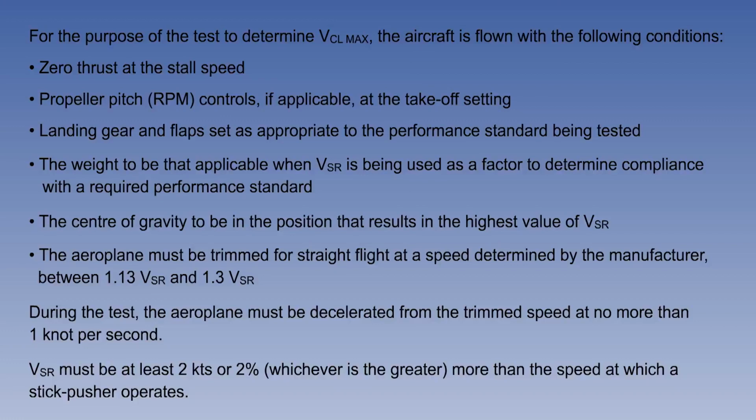VSR will vary with each of the conditions specified. Factors which affect VSR are thrust in excess of 0, wing contamination and load factor. One thing that does not affect indicated stall speeds, however, is density altitude.